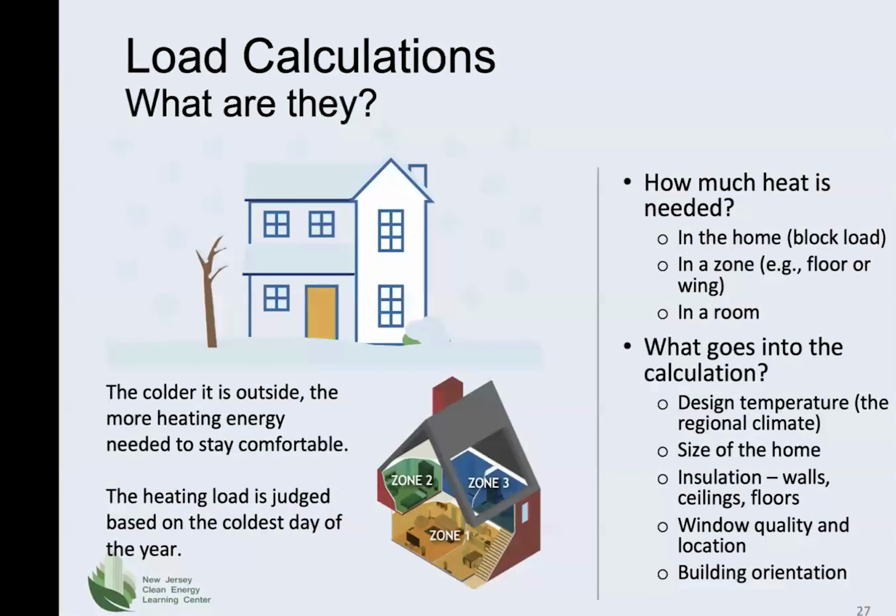There are 2 different load calculations that are typically done: the heating load and the cooling load. The instantaneous heat load is the amount of heat needed at any given time to maintain a comfortable indoor environment. The heat lost through the building envelope must be replaced by an equal amount of heat supplied to the indoor space. A house can be thought of as a box with exterior walls, a roof, and a basement. The walls and roof have an insulation or R value that slows down the rate of heat loss to the outside air surrounding the house.